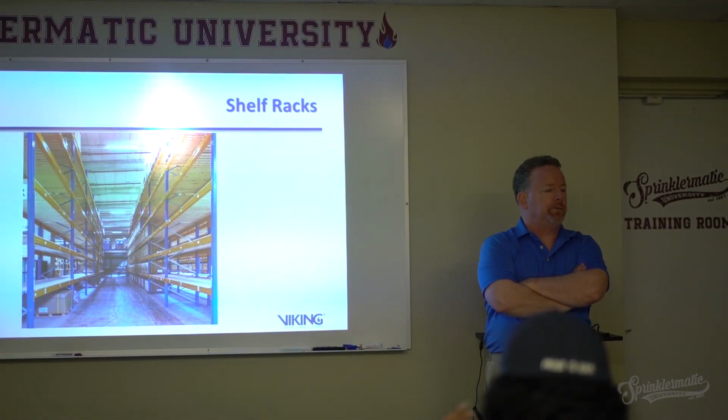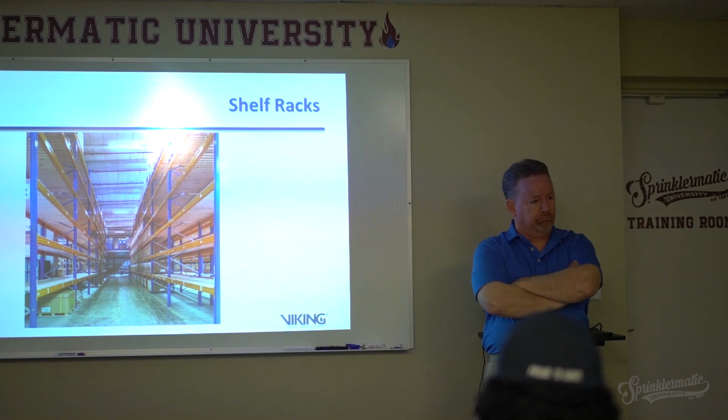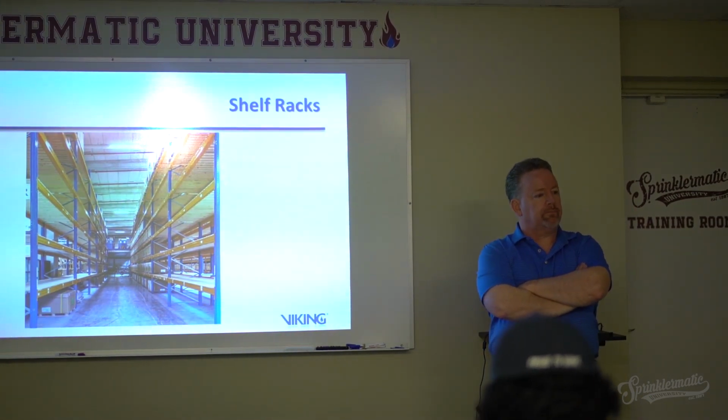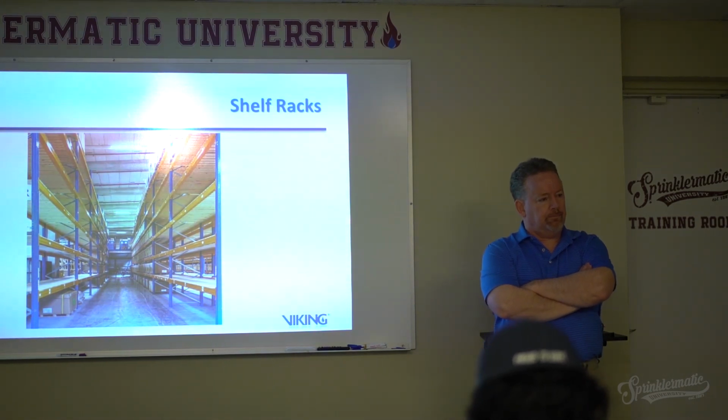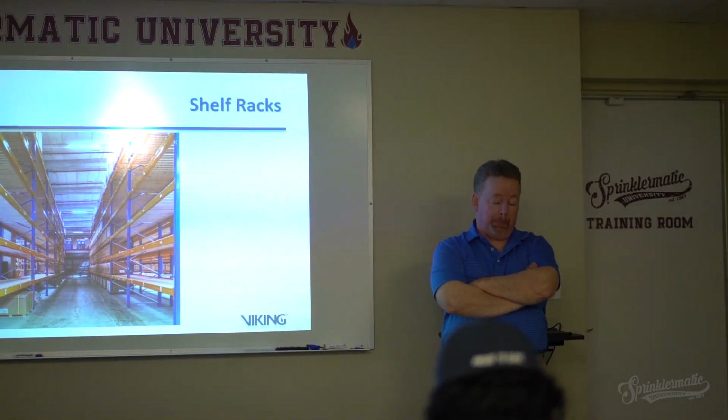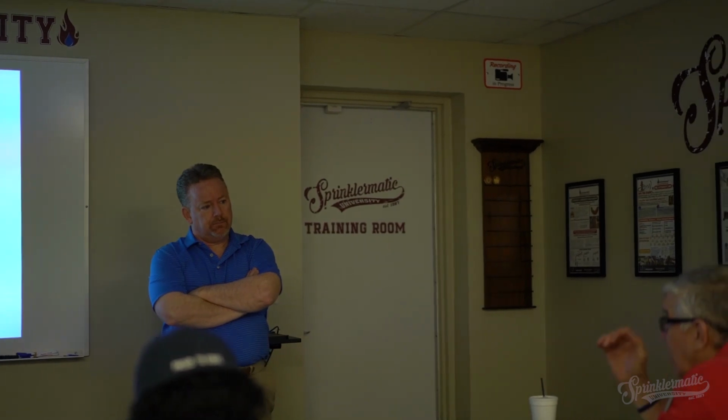I look and I see that we've got solid shelves. So it sounds to me like that's a dead giveaway that you've exceeded or violated the design. Okay. Yeah. Solid shelves have to have in-rack sprinklers. Well, solid shelves are a red flag for you to go back and question the design. There you go. Okay, they're absolutely a red flag.